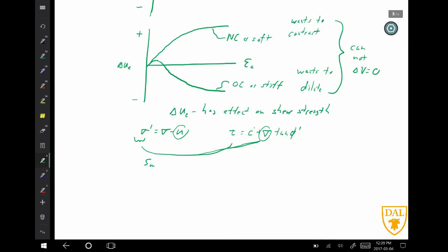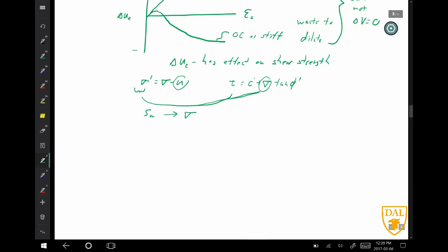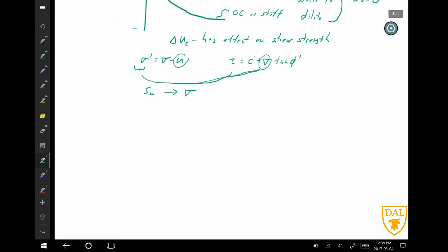And we simply look at it in terms of the total stresses being applied to the specimen and how much it can handle. And all the effective stress, pore pressure behavior is implicit to this. So we basically simplify it all down, okay?